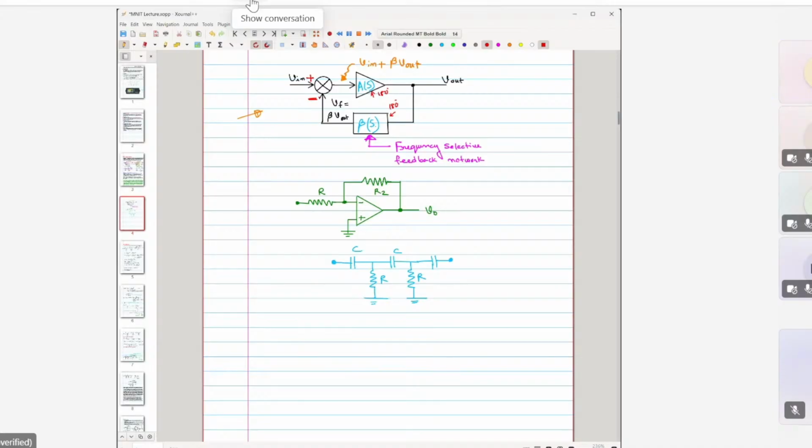Okay. Now, how can you design these oscillators in terms of circuit? For example, we need an amplifier which can produce 180-degree phase shift. So we can use different types of amplifier. One of the amplifiers using op-amp, we term it as an inverting amplifier.